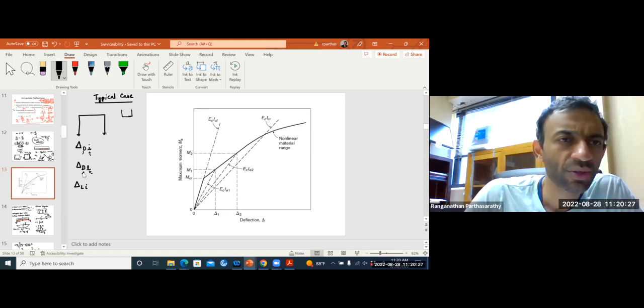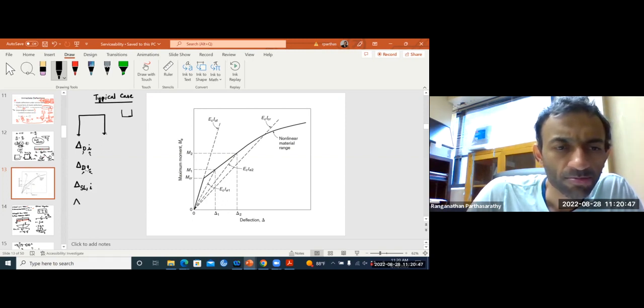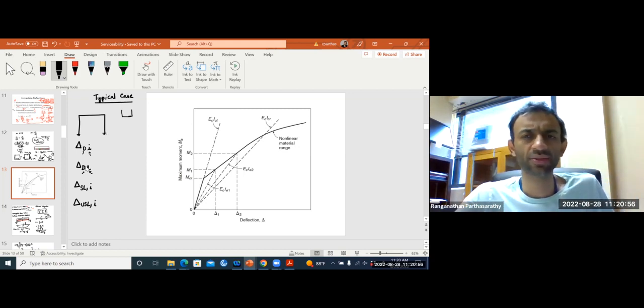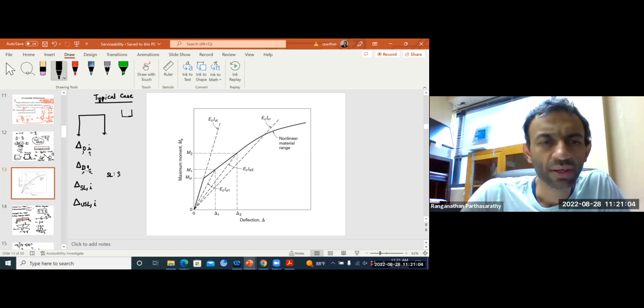Okay. So, before we write about live load, we note one thing, that live load will be broken into two parts. So I will write SLI, USLI. So let's just understand what are all these notations. What is SL? SL is sustained part of live load.